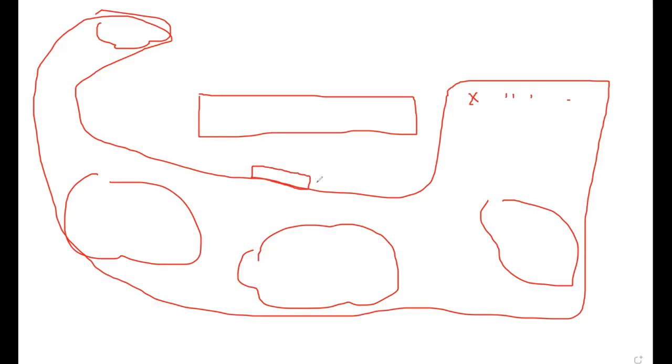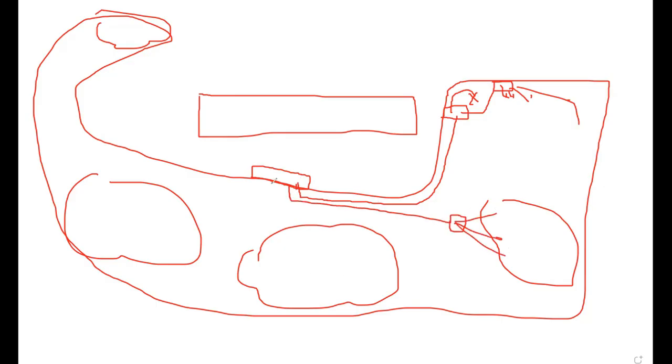So what I will do, I am taking one connection to here. I place another distribution board, a sub distribution board. And from the sub distribution board, it is connected to the motors and to the switchboards. And from these switchboards, it's connected to the fans, lights, everything. Similarly, I'm having one more sub distribution board here, and from here to here. So like that. This is how you are doing this.